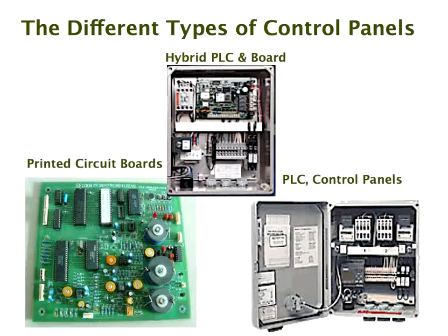the pre-treatment system and the drip should be on the same control panel. Now, there's no reason that they can't be on the same control panel if that control panel is set up to do all the functions that the drip panel requires. Sometimes people might take a control panel for a treatment plant and add on limited pieces, and then of course we don't get the control and the collection of data that we'd like to see.